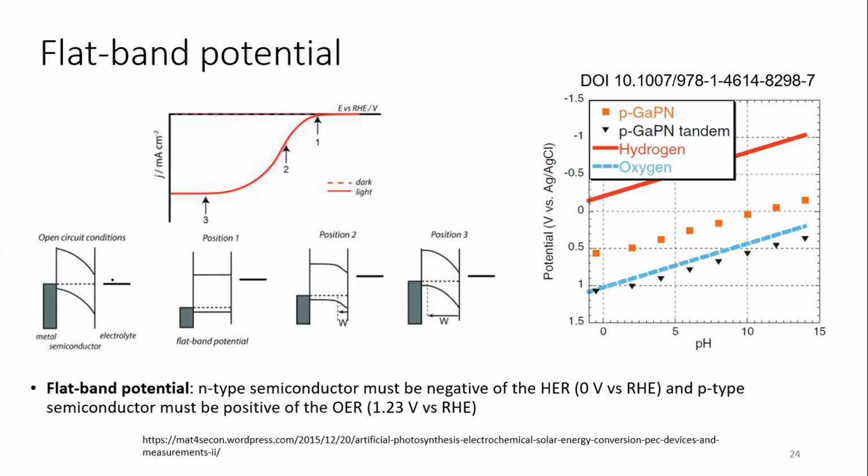After that we get this equilibrium state. Since it's a p-type semiconductor, electrons will be transferred from the liquid medium to the semiconductor. So the semiconductor gets some extra electrons close to the surface, and we represent that in the energy band diagram as downward band bending. That means it has excess electrons at the surface, so you get this downward band bending.